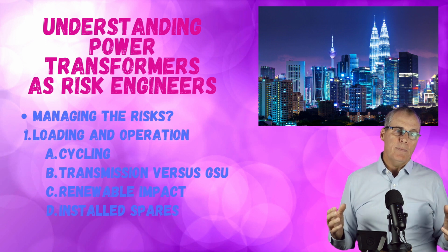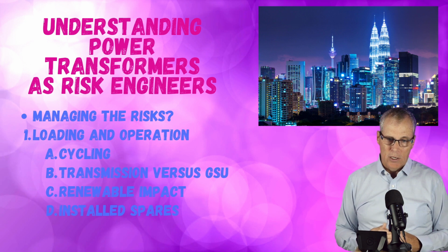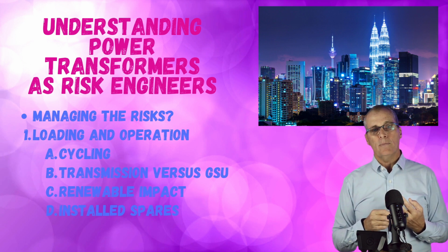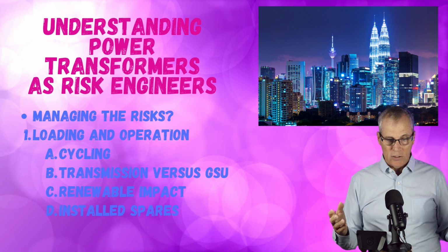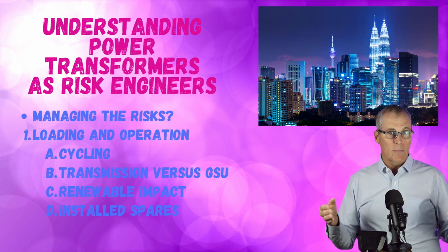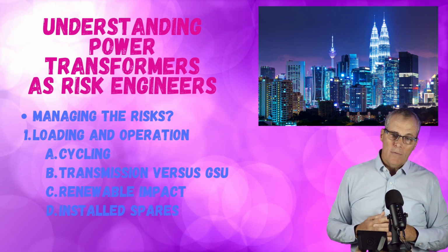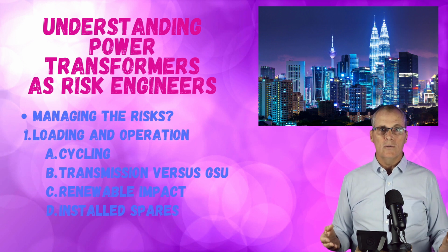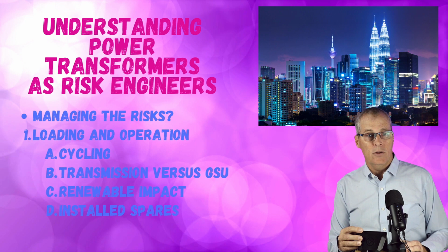Now, installed spares, if you have that, wonderful. And like I said, in this one substation, we had a three-phase bank, we had an installed spare. Even 60 years ago, they realized that that was a critical substation and that there better be some redundancy and reliability if you were supplying a downtown metropolis, right? All right, so if you have installed spares, it's probably going to be maybe two smaller units, two 60s, but not likely to have two 100% capacity transformers, just one sitting there not doing anything.